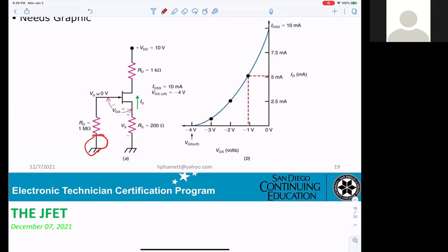Mr. Pham, depending on the application, for JFET or bipolar, how do you know which one you want? Is it based on your application? Do you want something that's on all the time or off all the time? How do you determine that? Basically, if they want high gain, they don't use JFET. Only the bipolar CE amplifier gives you more gain.